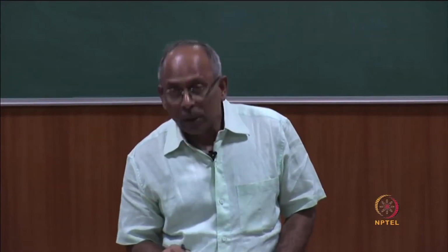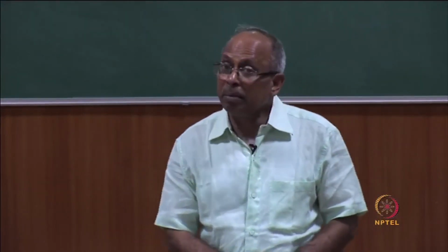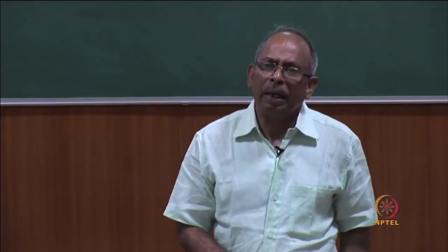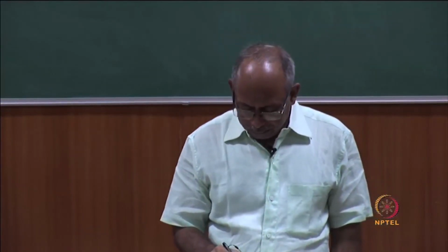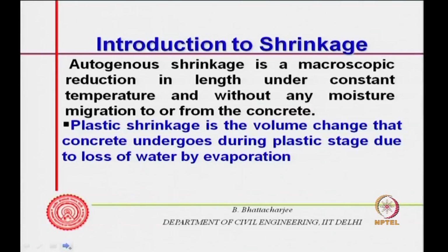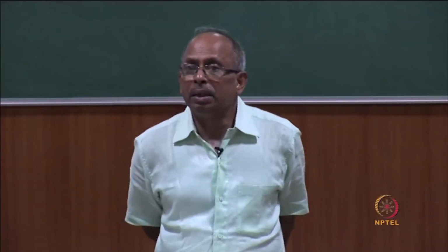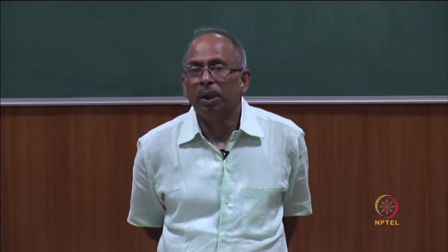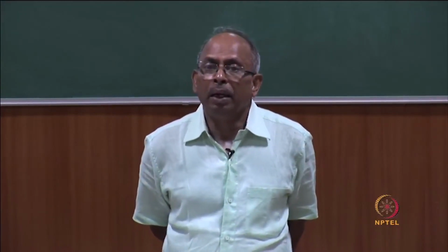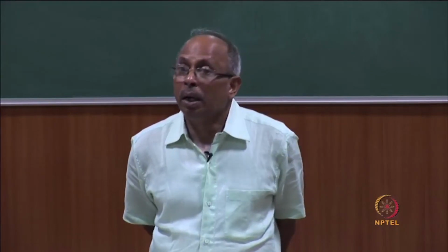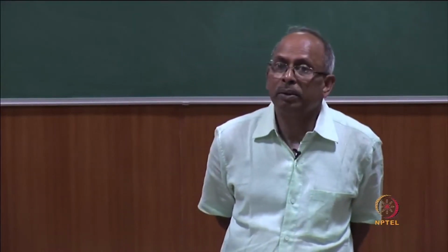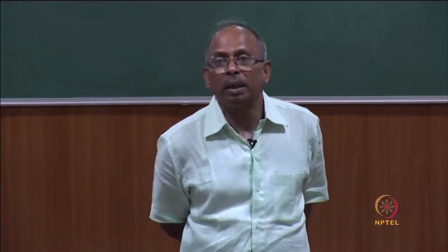Now, the settlement has a role; in fact, plastic settlement can cause some sort of cracking, I think I mentioned some day earlier. All right. Then drying shrinkage. Drying shrinkage occurs in hardened concrete as it is drying. So, once it is solidified and is now hardening, at this stage if there is evaporation loss, the loss of water from the gel system can cause shrinkage, and this is called drying shrinkage.